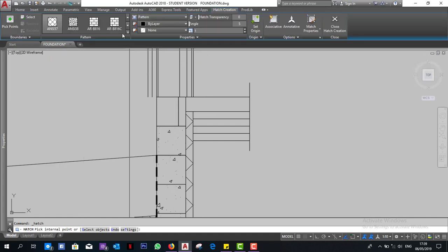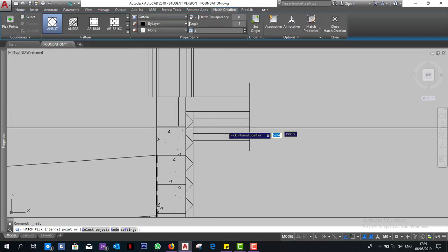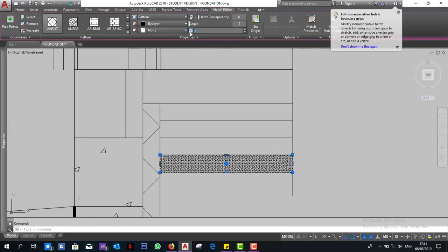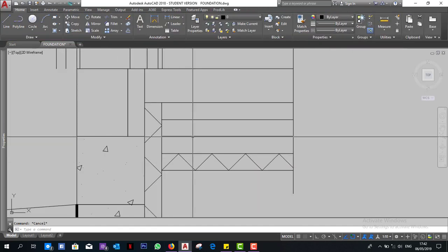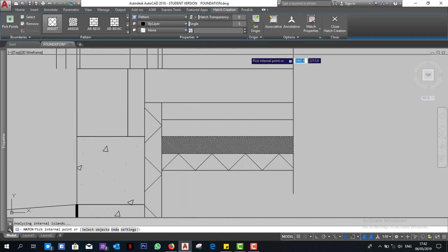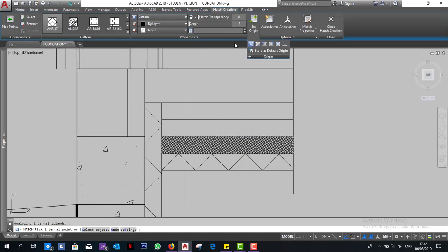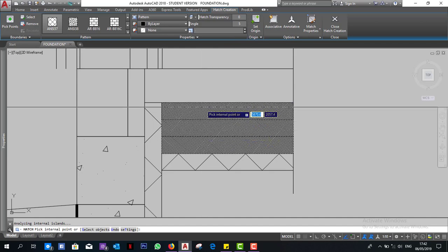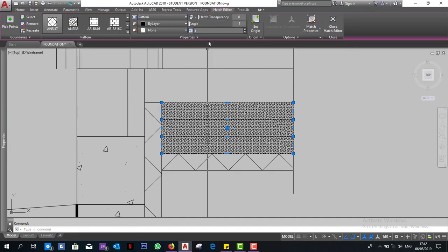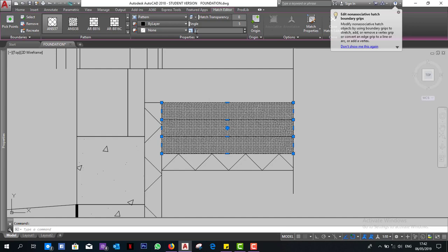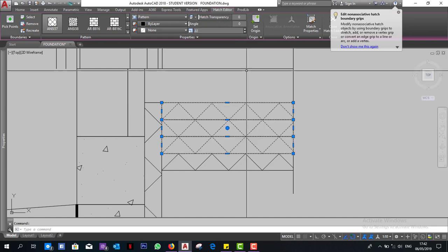Now we are going to place the hatches. For that we go to offset 37, we place those in here, 22 the scale, now the angle is 0. So yes, now it's good. Now we just place that. Oh, sorry. Yeah, we're good. We place the hatches. Now we select them all. We make the scale 22. We make the angle 0.